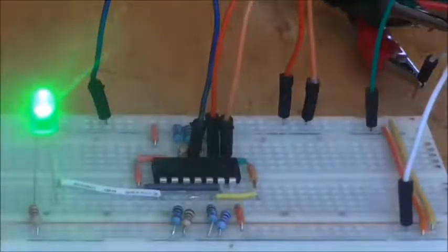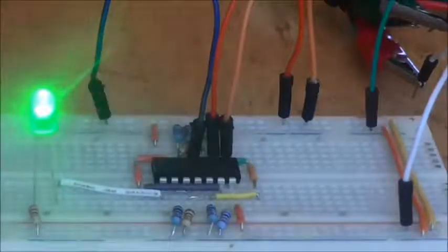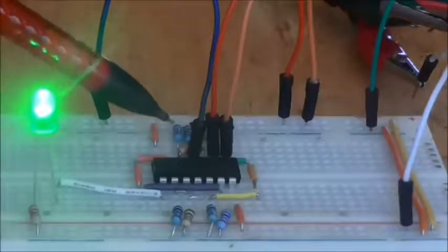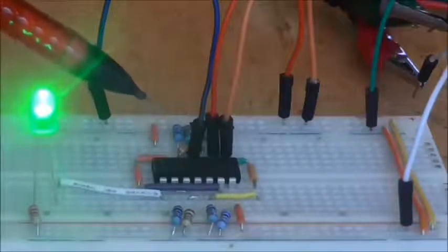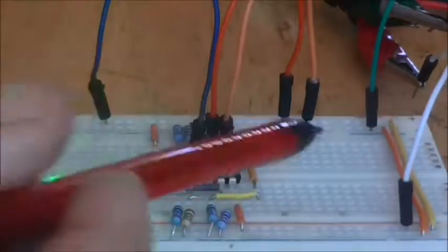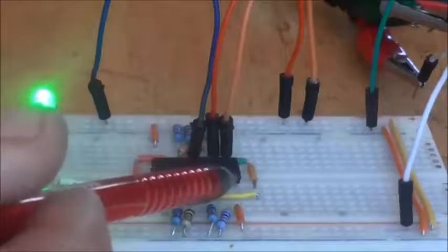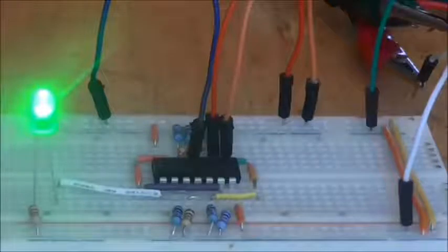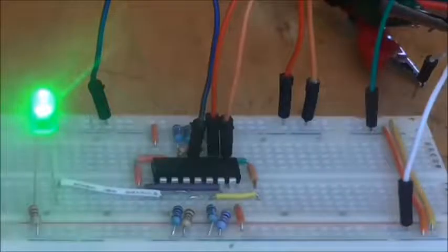Well, what we're going to do next then is a NAND gate, and this is it, or rather 4 of them, all packaged up in this 14-pin chip here. This is a 74HC00M. And what you get in there is 4 NAND gates plus the power supply, positive there and the negative there. If you wire them up properly, like we saw in the drawing, then you can turn these 4 NAND gates into an AND gate.